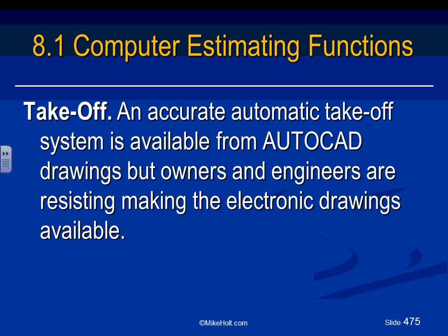Okay, accurate. So like I said, guys, for takeoff you can interface AutoCAD. Just be aware that there's on-screen takeoff. There's also AutoCAD interface. McCormick has a component where you input the drawing in AutoCAD format into McCormick. You identify the blocks that you're using, and the software will go there and count all your receptacles and switches and so forth. Input them into the software, assign the labor units and everything else to them, so you don't have to do the takeoff by hand.